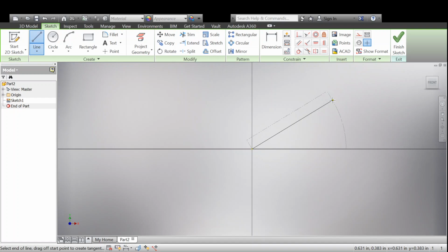Now I want to change the angle. Instead of pressing enter, if you press enter right now, it'll set this to be 2 in length, and it'll choose that angle automatically. But if I want to make it another angle, press tab on your keyboard. It's right above the caps lock button. It should move you over to the angle now. I'll do it on mine. When I press tab, take a look at what happens.